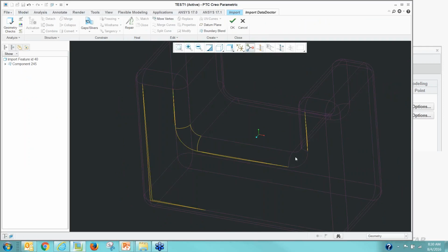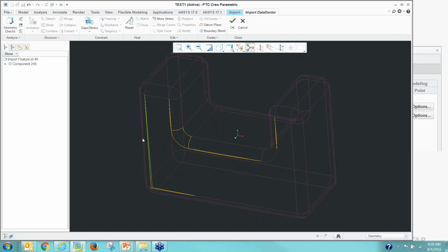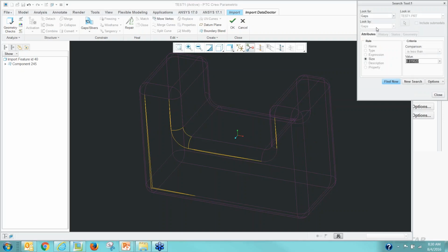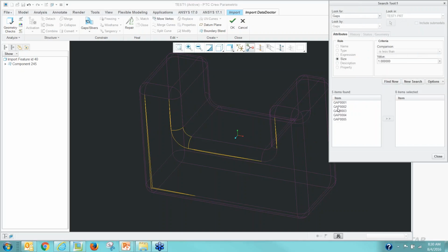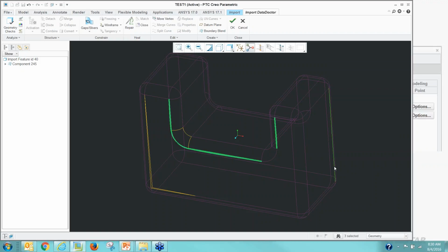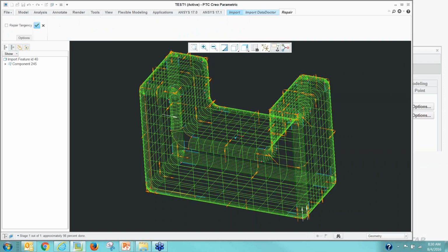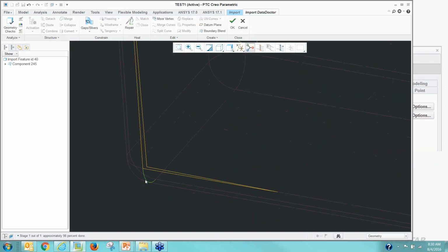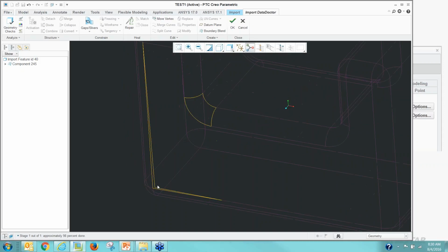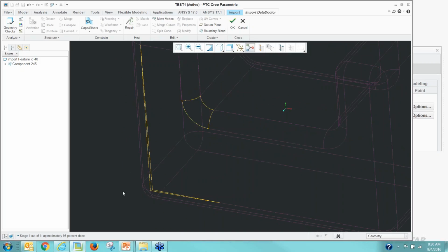I could have used gaps to fix that, but could I have used other methods? For example, when I searched for gaps, this has happened to me many times where, in this case, I selected every gap and it added to the wireframe, and sometimes I've seen it wouldn't even add it to the wireframe, or it wouldn't repair like I showed in this example. So let's say I picked these little tiny gaps and I'm adding that to the wireframe and I repaired it. But let's say these type of gaps, like variable values, it couldn't do it for whatever reason, right?